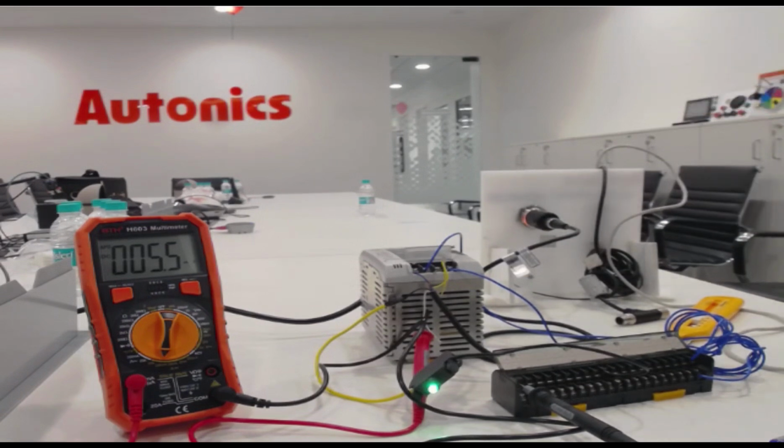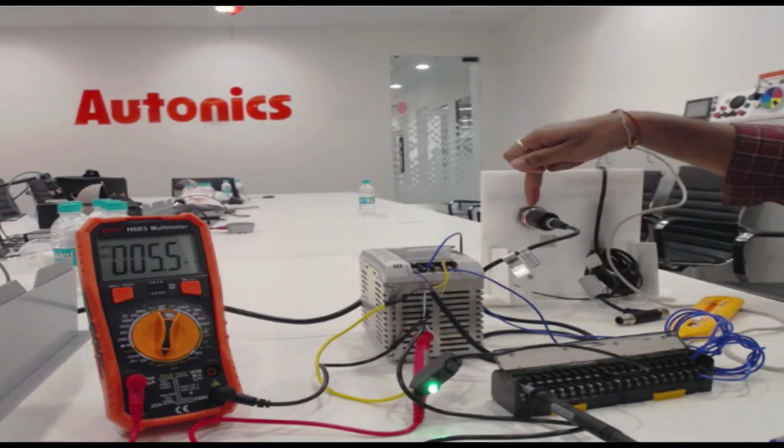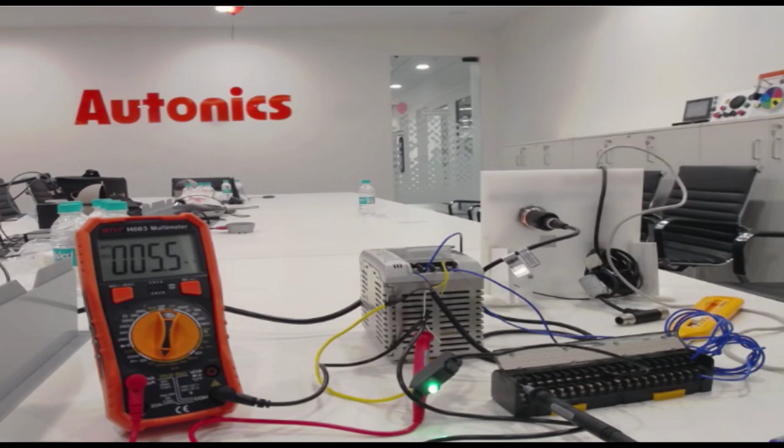And we can see our output is also on, and here also the orange color status is on for digital output. Now my bottle is at set point 1. Below set point 1, for all the distance, the output will be on. We can verify the same.